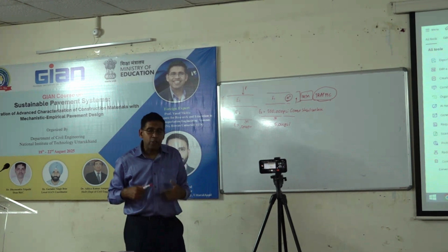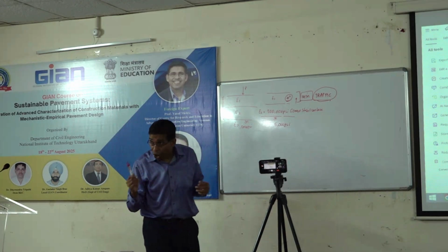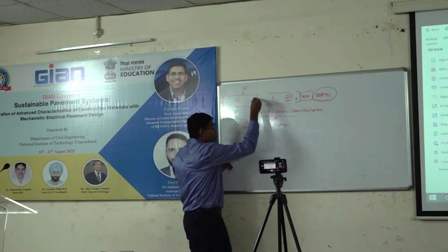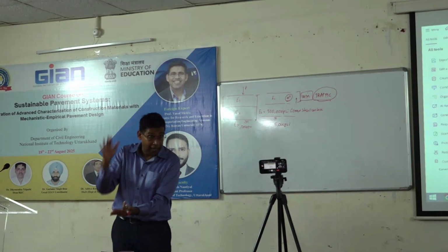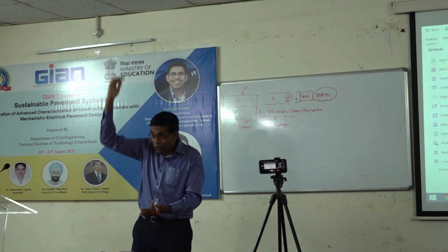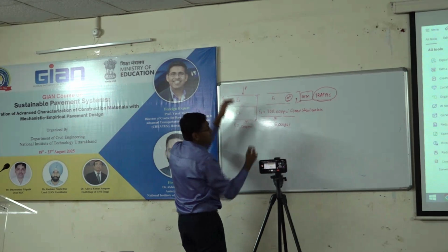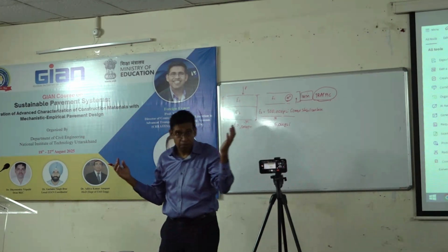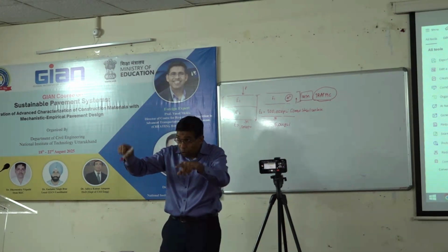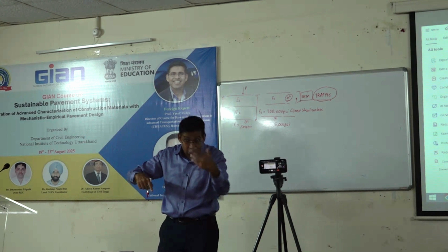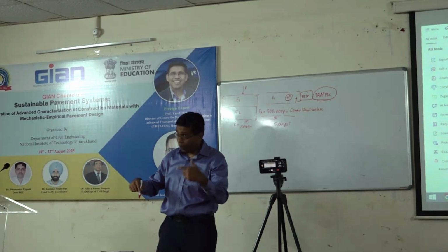Couple of things. When I do the cost optimization, many times you will be locked by the grade of the roadway. Right? I cannot increase the height of the roadway. There's a bridge coming over. So I might be locked, this entire distance cannot go up by more than 4 feet. I'm locked by that constraint. Now you have one more constraint there, right? You have to excavate, you have to remove the soil if I need a weaker soil. There's a cost to that, right? Or I provide a better material.